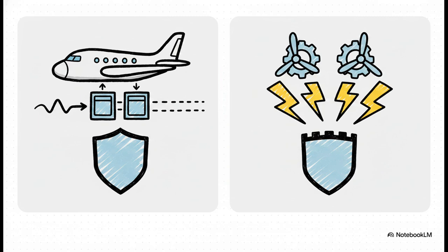Now, this strict hierarchy builds some incredible fault tolerance. For instance, look at the TRUs. You have 2 of these transformer rectifier units in the nose, and they convert 115-volt AC power into 28-volt nominal DC power at 300 amps maximum. Get this, just these 2 TRUs alone can sustain the entire DC system if needed. On the flip side, the 2 engine-driven generators supply 28.5 volts DC and a massive 400 amps maximum once the engine speed exceeds 50% NH.